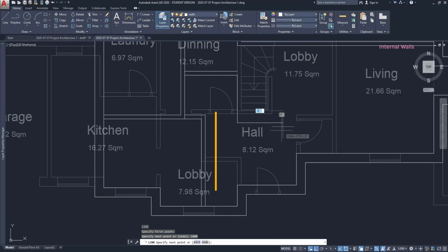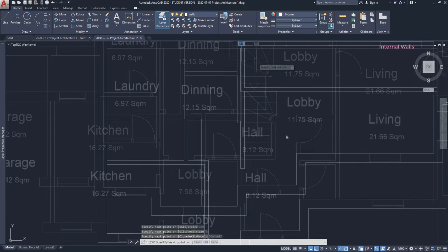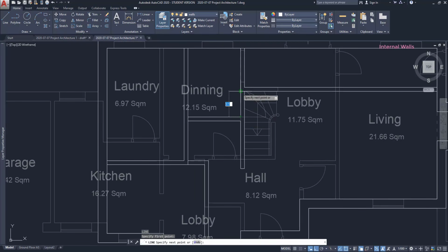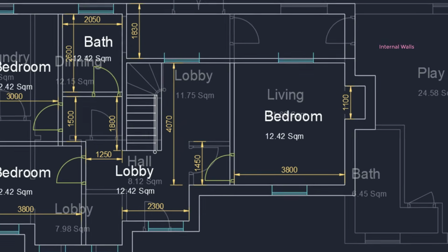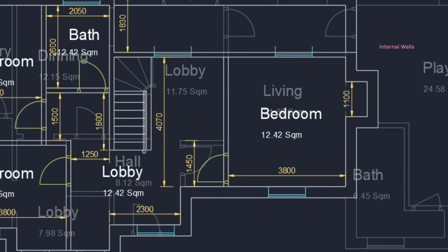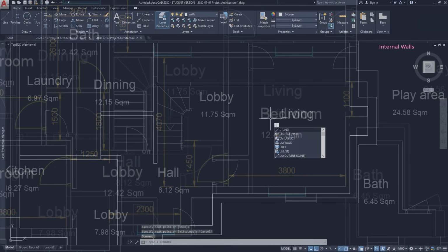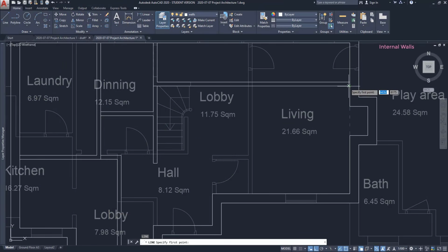Then draw a line with 150 and connect it there. Finally, draw the remaining line on this side. Finally, there I will make the wall that divides the bedroom at the left. I draw it exactly above the one at the ground floor. I can also still use the distances on the PDF file. You can see that they match the ones at the sketch.